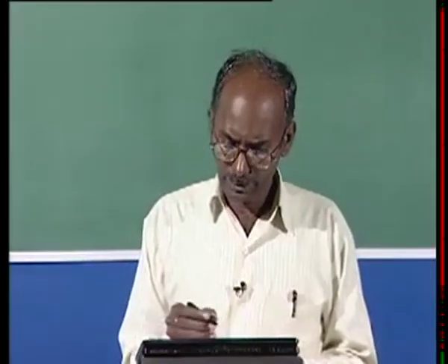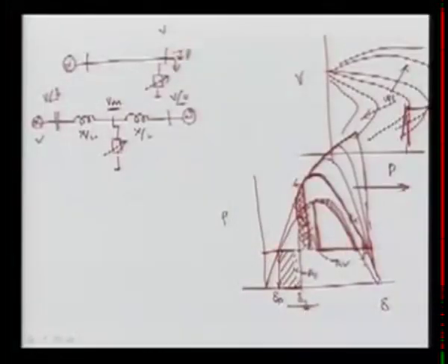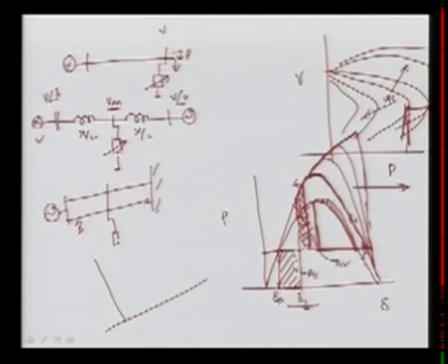So similarly we can also explain, let's suppose our system here is a generator which is feeding and connected with the two lines. Let's suppose we are putting a compensator here, and here is the infinite bus, and again we can now show for the other condition, the other system. Here it was a single line, now we are having two lines and a fault occurs here. We can show again the transient stability limit will be improved significantly.